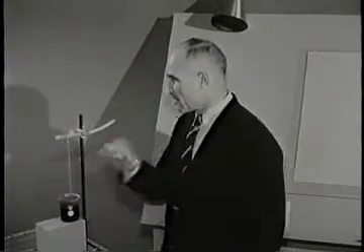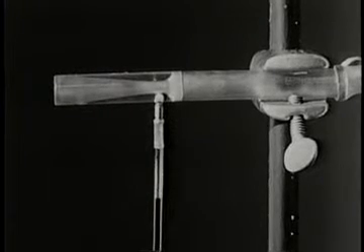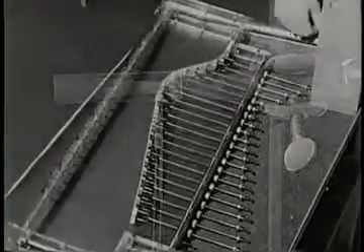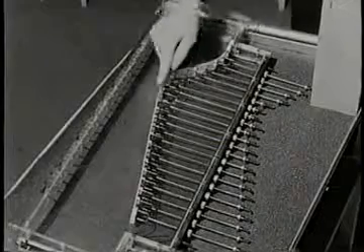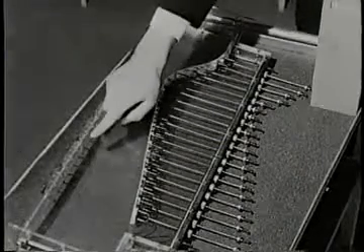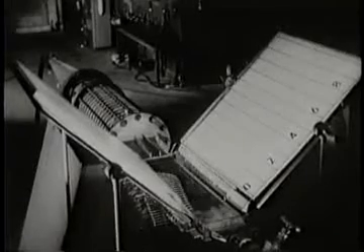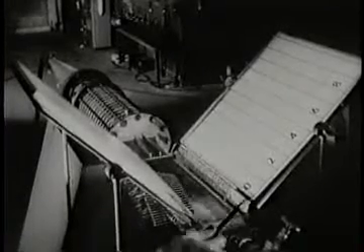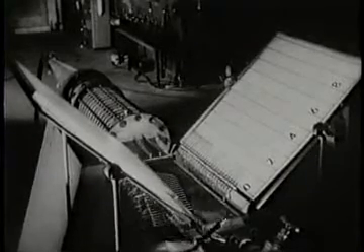Bernoulli's integral also explains how we can produce suction by blowing. To show how a venturi can produce low pressure, we have formed half of a symmetrical venturi in this special test section that has one adjustable wall. Here it is set up for test. These are inclined manometer boards to show the pressure distributions on the two walls. We will observe the lengths of the water columns looking down from a position directly above.